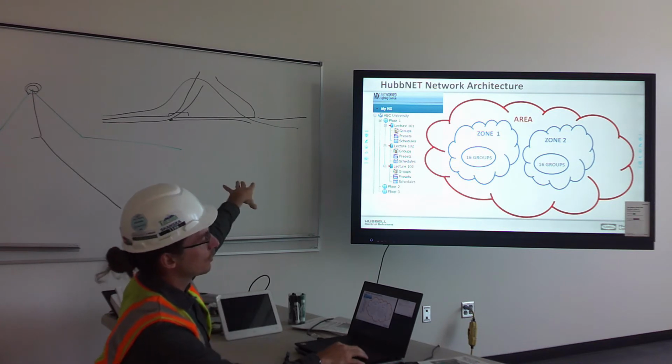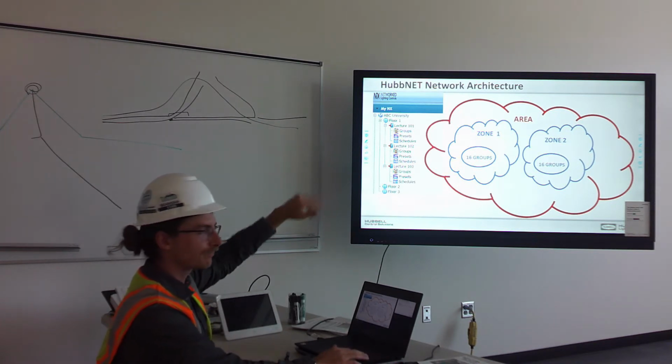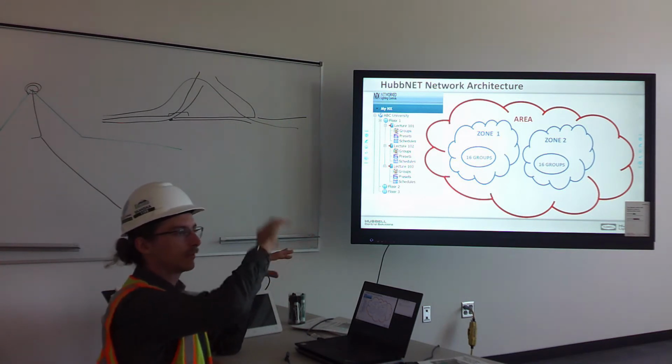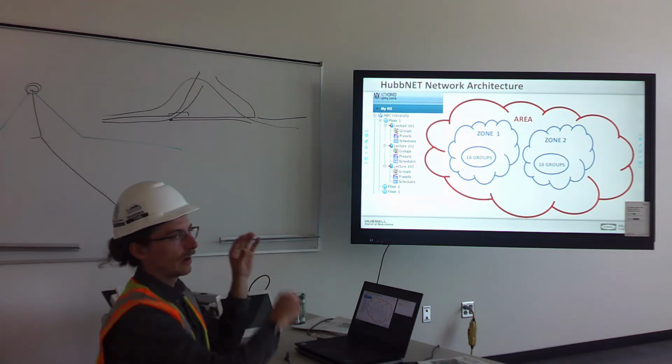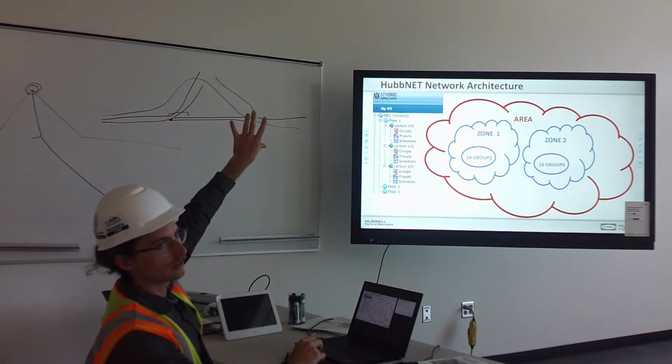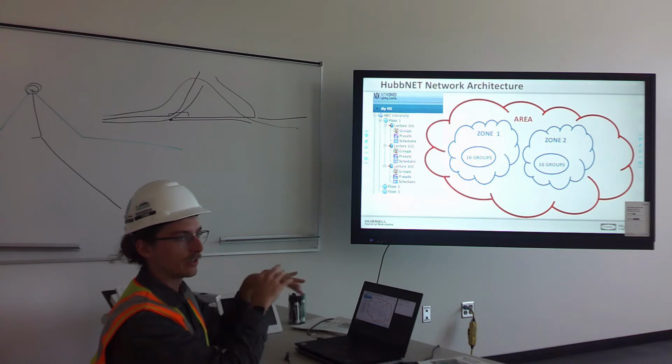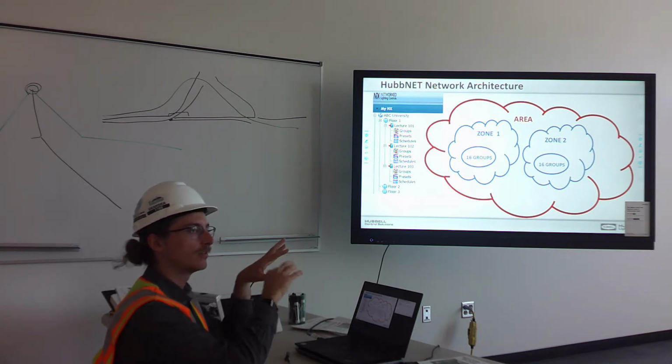Another example, that commons area: the big MV sign on the side of the wall is on its own bridge and controller. And the lights that are high up on the ceiling are on their own bridge and controller, but they're working together because they're programmed into the same zone.